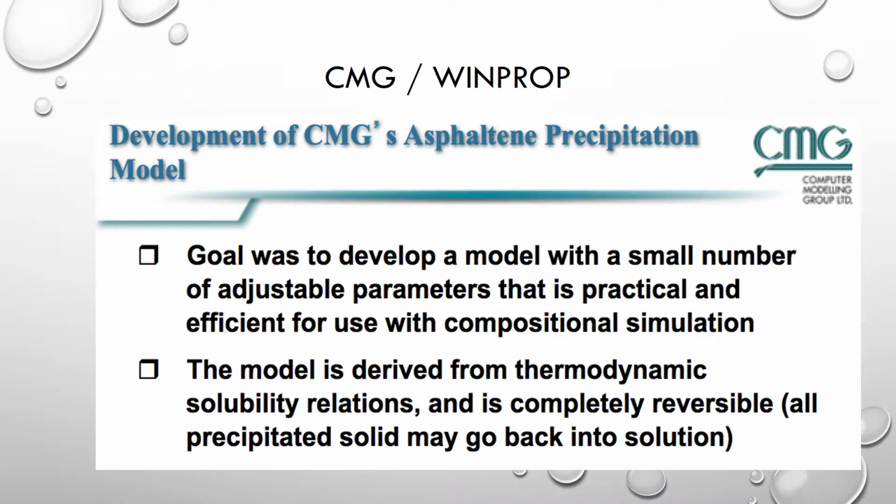From our contact at CMG, we have received additional SPE papers on modeling asphaltene precipitation, multiple WinProp data templates, and various example case studies run by CMG using the WinProp software. We were given over 150 pages of documents related to the use and execution of WinProp, along with other software that could relate to our project. This information will be paramount in being able to successfully model the reservoir fluids and the deposition of wax and asphaltene. CMG's goal was to develop WinProp as a user-friendly model with a small number of adjustable parameters to practically and efficiently simulate asphaltene and wax deposition.